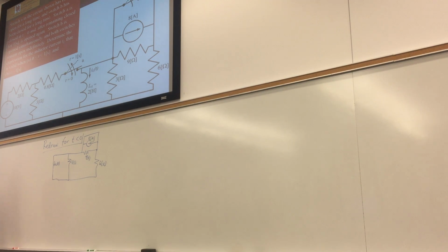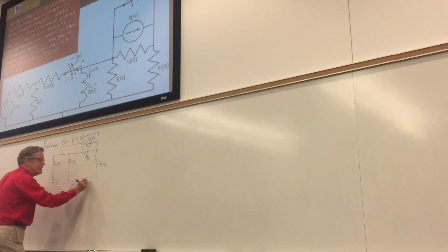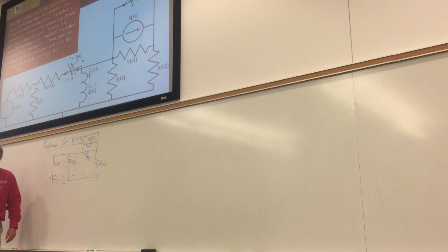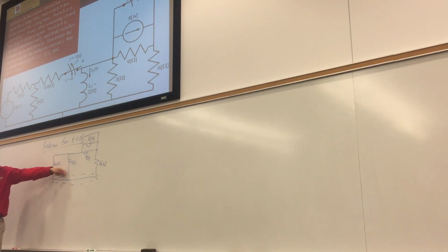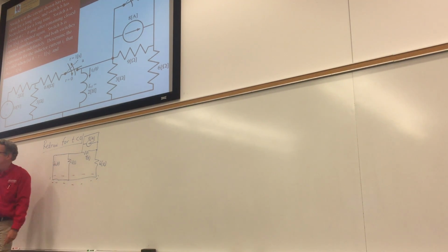The other alternative is to apply something like Kirchhoff's current law down here. There's one of the currents. What's that current? It's 0 because there's a wire across that 3 ohm resistor, right? Yep. How about the current through the 6 ohm resistor? It's 0 because it could be in series with the short. Being in series with the short is not the point.